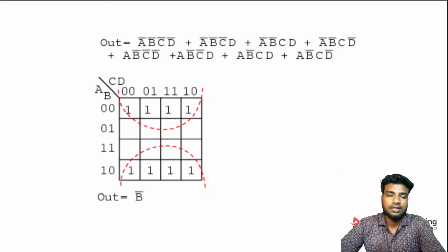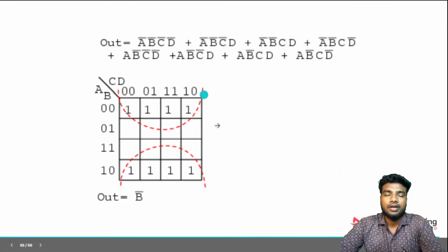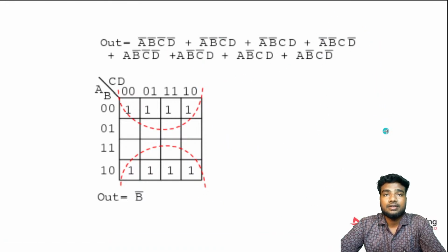Tomorrow we'll see some basic Verilog programs, like a mux, encoder, decoder, and circuits like a counter and shift register. We'll see how to write Verilog code for those, what the syntax is, what the data types of Verilog are, and what the levels of abstraction in Verilog are. It has a lot of levels of abstraction, like the behavioral model, the structural model, and the data flow modeling style. So it has a lot of styles to write Verilog code.